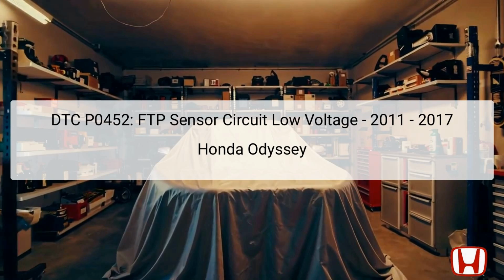The diagnostic trouble code DTC P0452 signifies an issue with the fuel tank pressure (FTP) sensor circuit, specifically indicating low voltage. The FTP sensor is a crucial component located on or near the fuel tank that monitors the pressure inside the fuel tank. It plays a vital role in the vehicle's evaporative emissions control system by helping ensure that fuel vapors are properly contained and managed.